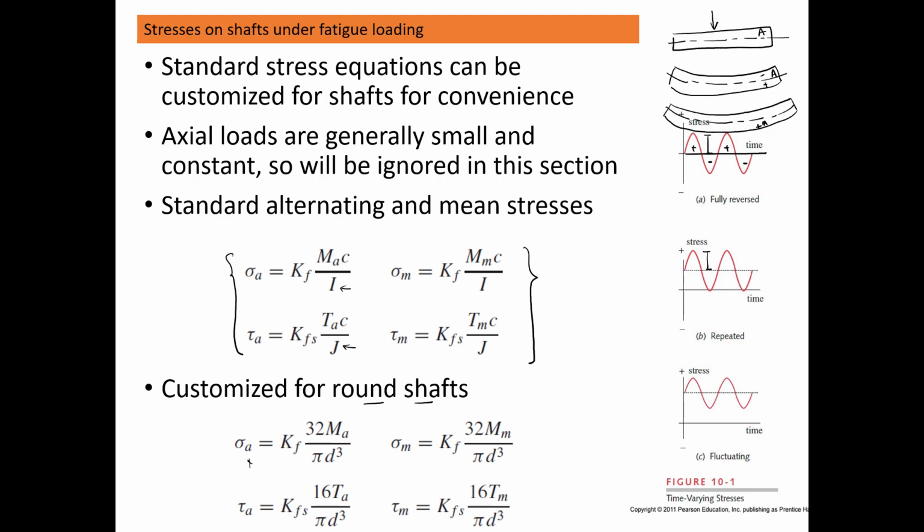And we're going to have the fully reversed case, which gives you the mean value for the force, for the stress, etc. Torque, so always we have the mean value 0, and the amplitude, or the alternating portion, is equal to the value itself, x max. So if we're doing bending, then M mean will be 0, the alternating portion Ma will be equal to the maximum moment, and so on. And the same discussion can be done for the torque.